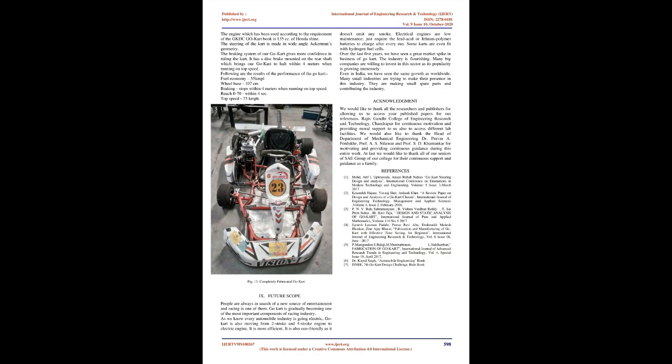C. Managing center of gravity and weight distribution. The heaviest components of the vehicle are managed and placed at a centralized position without hampering performance and safety, for example the placement of the fuel tank centrally behind the seat, and the centralized position of the driver's seat and steering system. Being a vehicle with low ground clearance and even mass distribution, the center of gravity is managed to be extremely low, thus giving good road grip, better turning ability and less tilt chances at high speed.